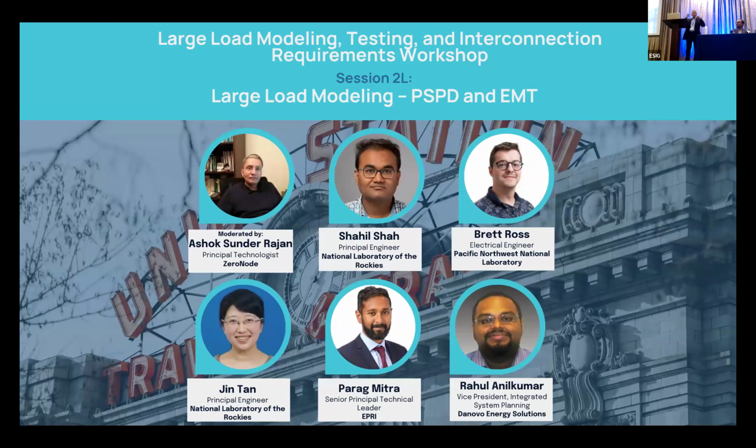I'm holding my laptop power adapter in my hand, and don't do what I'm going to do just now, okay? What I would suggest, to understand what these guys are modeling, is plug this end first into your laptop, take the power outlet end to your power outlet. So I'm saying connect the load first, then connect the source, and then go and jiggle the source. Has anybody tried what happens to the laptop? You will fry your laptop.